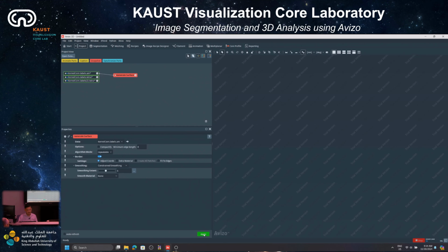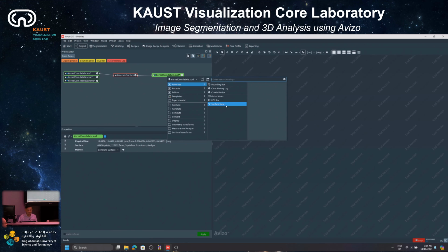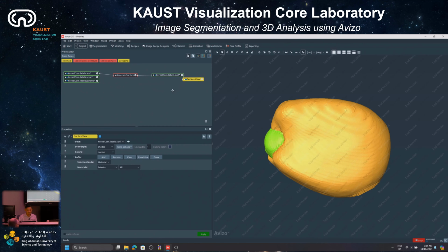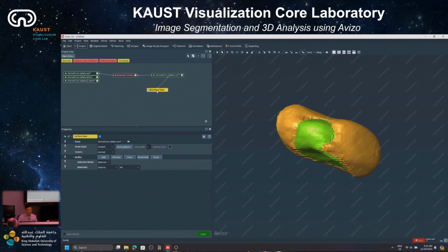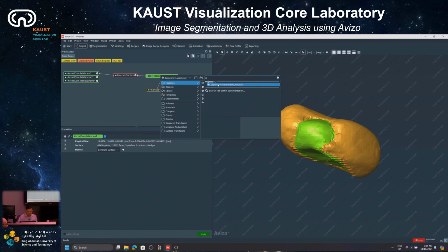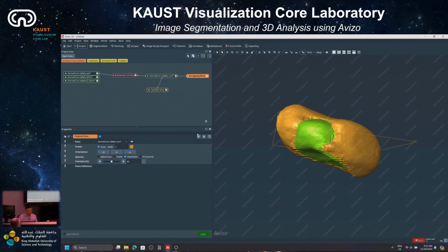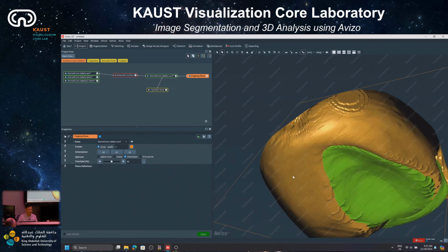And then click apply to create a surface on the original label data. Now you get the surface file, and with this surface, right click, select attach surface view to the surface, and create. Now you have this surface. Actually, if you look at this surface with a clipping plane, right click on the surface, then clipping, and I clip with the clipping function on the clipping plane property port. Clip. You can see the inside is a hollow surface. It's not a solid. So that's the difference.